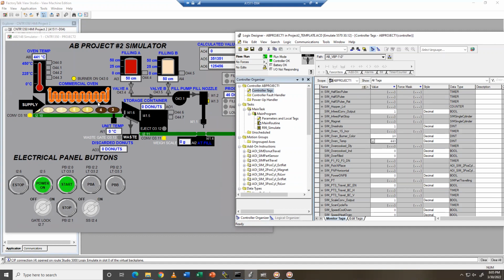So the code's in there, like it said, it's going to burn these if they're underneath the temperature, the heat for too long. You got to watch where the thermostat is, where the heating element is. You can't speed this up. So you may need to heat the unit up, but potentially pulse this output on and off.